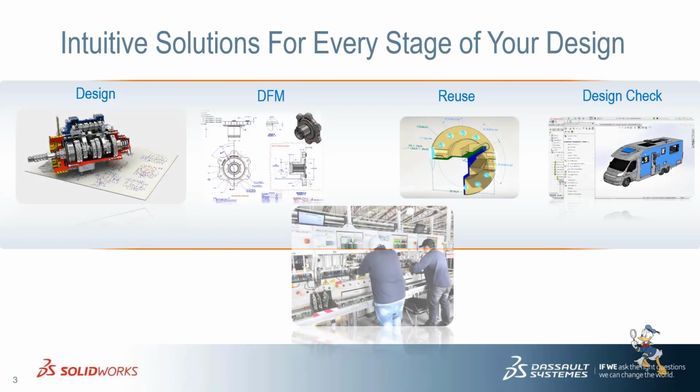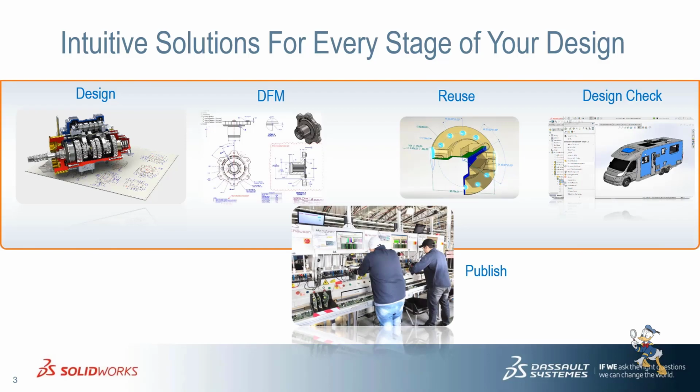We have some stages of the design. First we need to design the CAD models, then we need to do manufacturing drawings. We can design the models with reusability, so we can use that model in further models as well. We can do a design check if we need interference detection. If we have some interference between models, we need to do interference detection prior to releasing the model. Then we need to publish. Publish means we create our drawings, create e-drawings, and generate our model specifically for the shop floor. So let's see how these things happen.